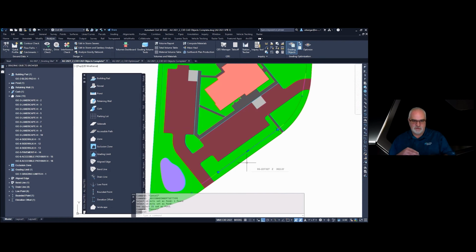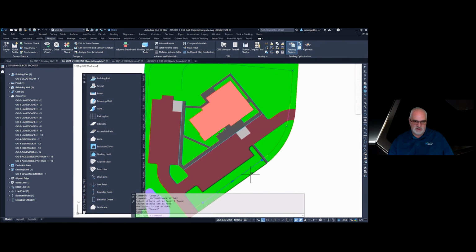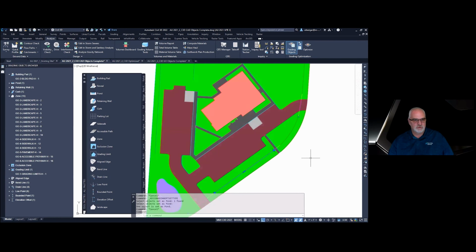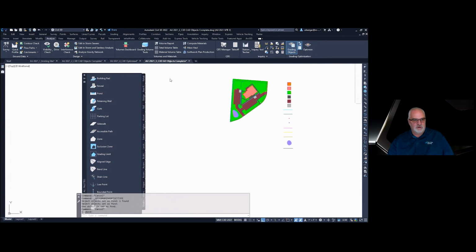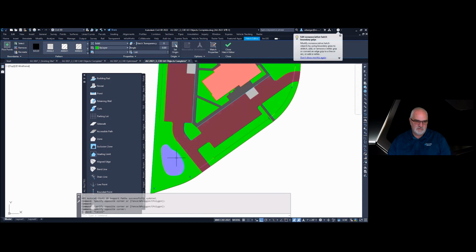A drain line is just going to make sure it flows from point A to point B. It may kind of do a little roller coaster look, but even though it's got a positive drain, a lined edge is going to help fix that elevation. So I've stacked a lined edge on top of my drain lines in this area because I need it to be more consistent. So I'm going to go ahead and jump to this drawing where I've already got it. Everything is defined in here. So if I look at my constraints, everything is set.